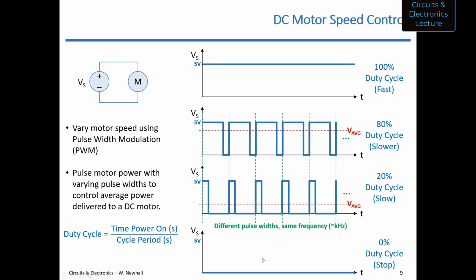And you could even see in your lab when you flash your infrared emitter and you look at the voltage out of the detector, there's flashing going on, but if you replace that emitter with an LED, you wouldn't be able to see the flashing above maybe 30 or 40 hertz. So in this case, it's the mass of the rotor that is acting as that low pass filter.